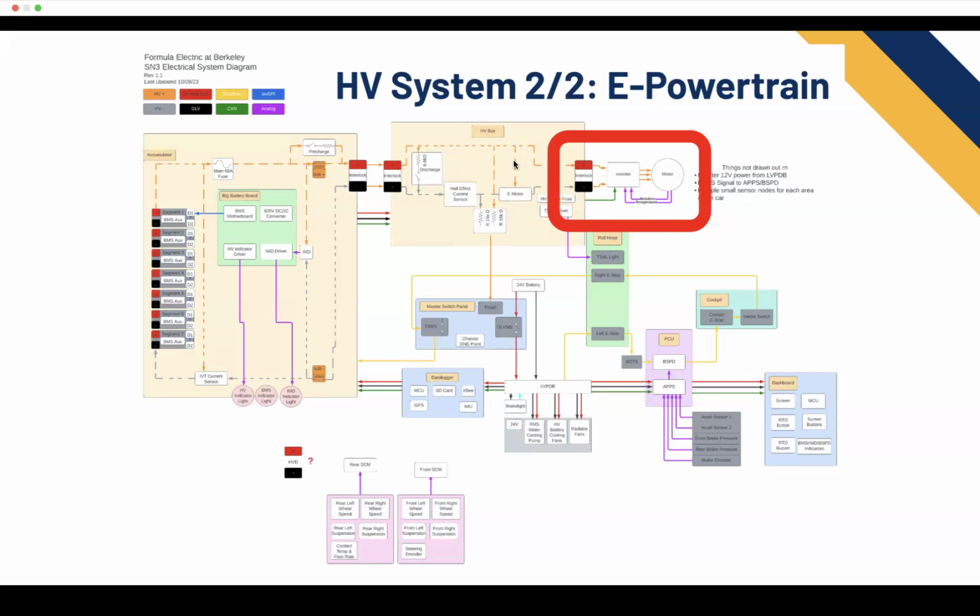And then it also has an Anderson. There's a wire that comes out of it with an Anderson crimped onto the end. So then in the HV box we have to put another Anderson that connects to an eyelet that's bolted into this bus bar, so it can sense the voltage and the current. What it does with that is calculate the power, because there's competition rules that you can't go above 80 kilowatts of power. It logs all the data internally, and then they come up to your car after each event, download all your data, and check you to make sure you don't go over that.